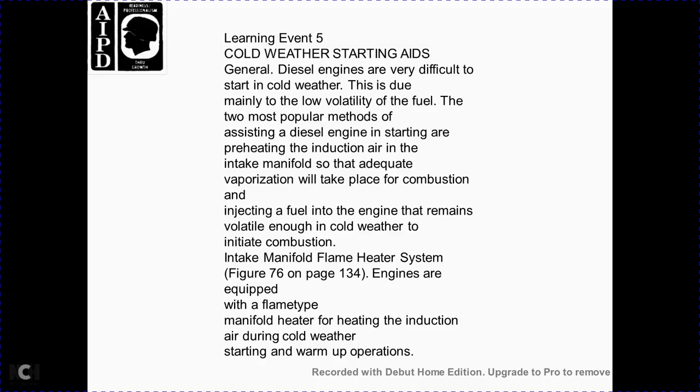Learning event number 5, cold weather starting aid. Diesel engines are generally difficult to start in cold weather, mainly because of the low volatility of the fuel. The most popular method of assisting the diesel engine is preheating the intake air in the intake manifold so adequate vaporization takes place for combustion, since fuel injected into the air remains insufficiently volatile in cold weather to initiate combustion. This is the intake manifold flame heater system.